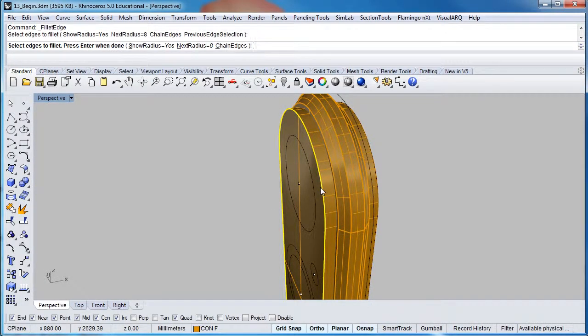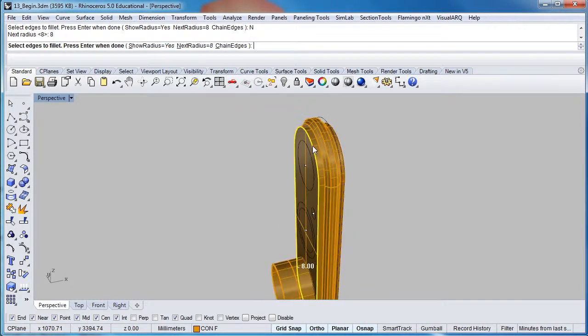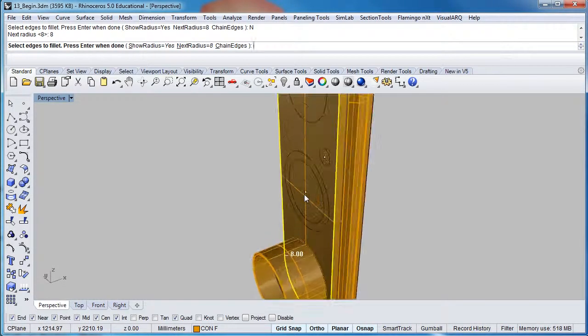So select the element, and as with the previous one where you're measuring the distance, N specifies the radius. It probably by default will be listed as 1, so you need to type N, enter, then put in the distance required. In this particular case it will be 8, so you can confirm that. On the next radius it says equal 8, and then we can simply select the edge we want. You can see it's listed there.